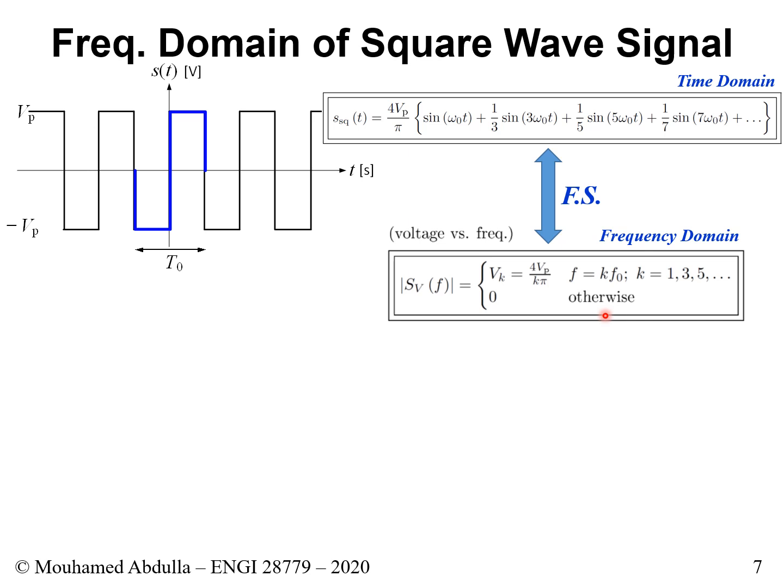Okay. Now, what if we want to see the frequency domain not in terms of voltage versus frequency? We want to see it in terms of dBm, like with a spectrum analyzer. How would we modify this? Well, this is straightforward. We simply take the peak value, which is this thing here, and we change it into the RMS value. And don't forget, you're not finding the RMS of a square wave. You want to find the RMS of a sinusoid, because you're looking at sinusoids: the RMS value of each sinusoid. So we change this peak value into a VRMS.